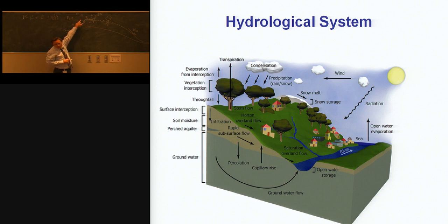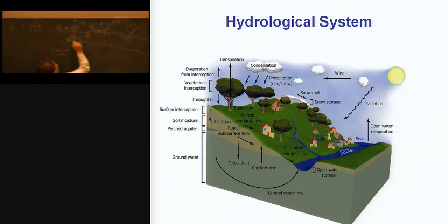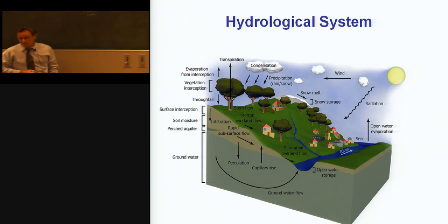Let's first, we have water here in the soil storage. Therefore it's a soil storage change per time. So as soon as water is stored here on the soil surface, it's a dS/dt, but I call that SS for storage on the soil. If the water infiltrates into the soil zone, then we have here in this unsaturated zone a dS/dt for, I call it SU, for unsaturated zone.